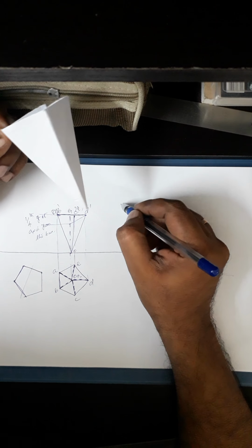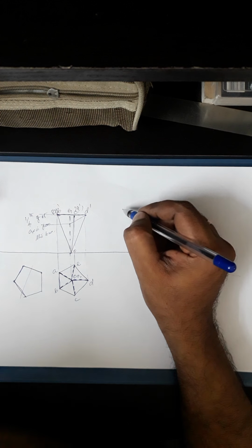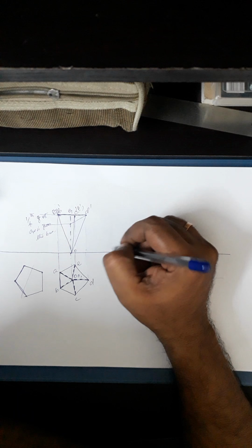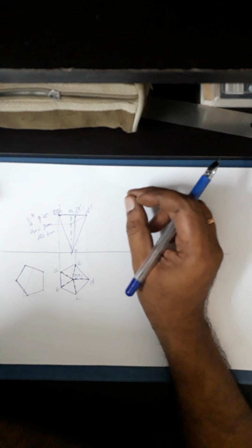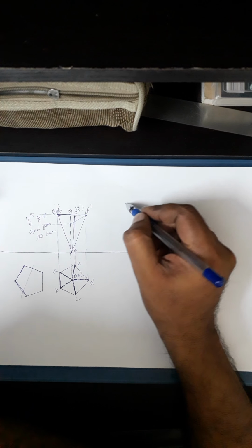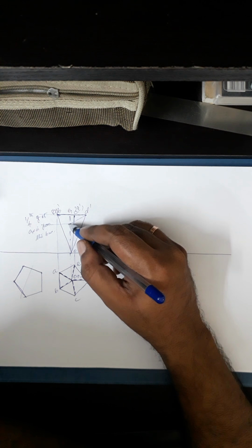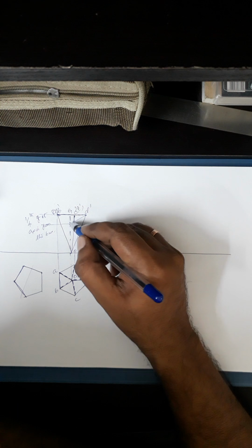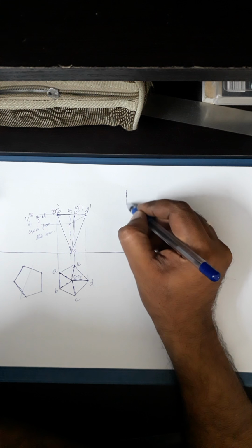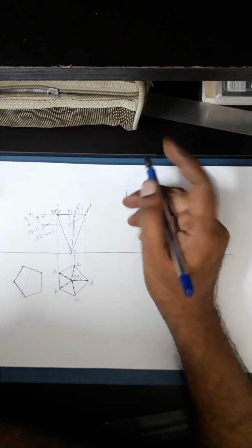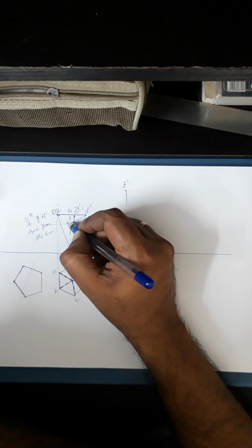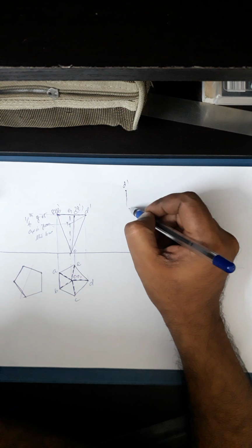Okay, so then in the same procedure as in the case of prisms, you have to draw it well above so that nothing should touch your XY line. Freely suspended, it should be suspended above the ground. So nothing should rest on HB. In that case, I'll go for having this construction. Anyway, I know this length. I can take this length and draw a vertical line. Let it be very thin, this is not important. So go for marking that point. So this is D dash, whereas this is the point, I'll say some point P, right? So this is P.